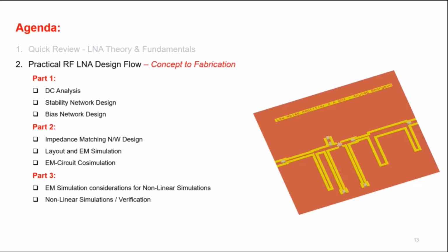How will we verify the blocker tolerance simulation of a receiver? Yeah, so that again is very subjective. So Soham asked this question. Soham, that's very subjective. I would say please work with your local Keysight team. They will understand the requirement a little more carefully and suggest a solution. Depending upon how deep you want to go, you can do things in ADS very easily, or we can use a system level tool from Keysight called SystemVue, which can do much better selectivity and sensitivity analysis and blocker analysis and so on.